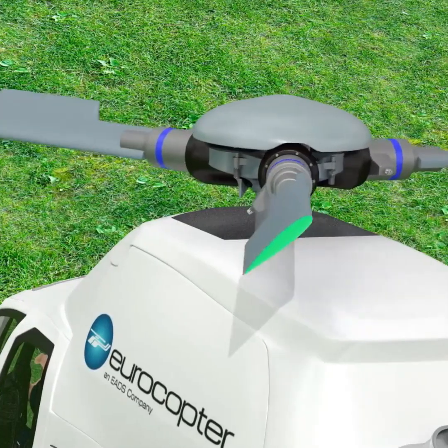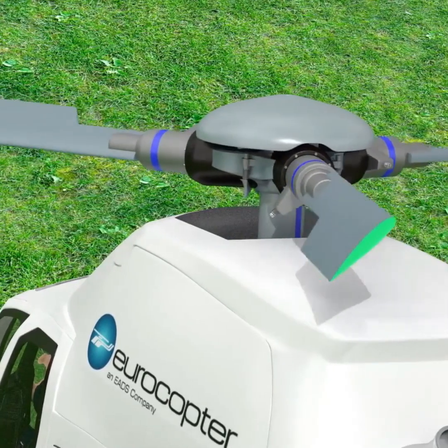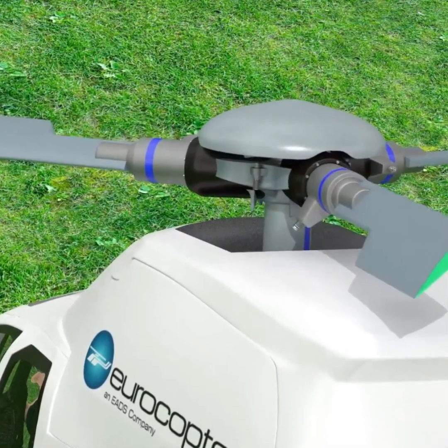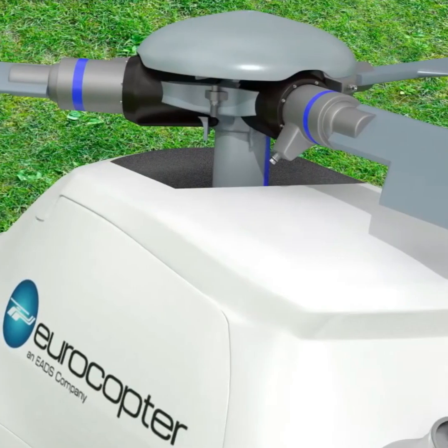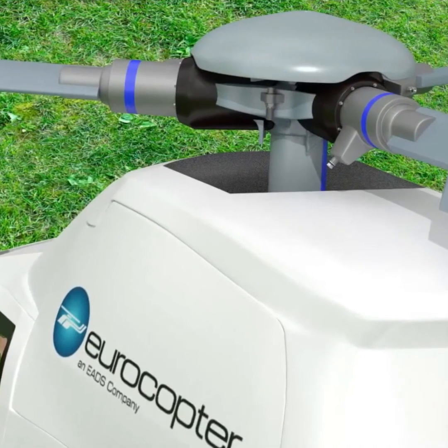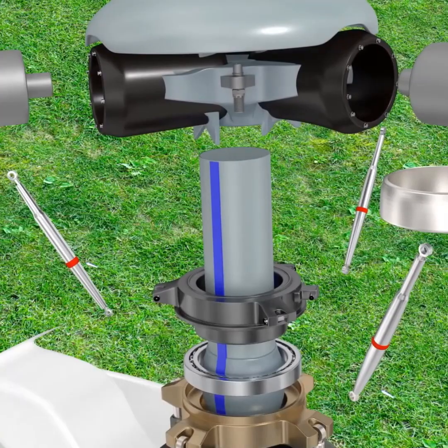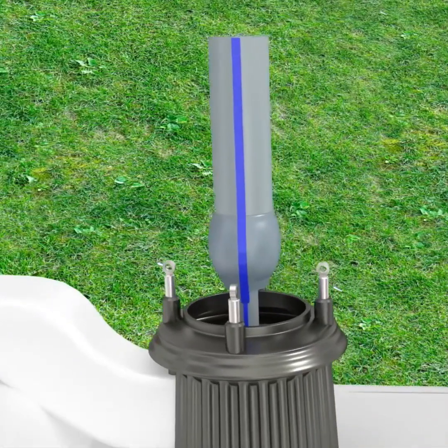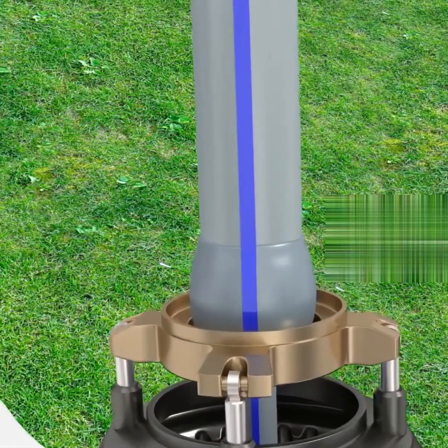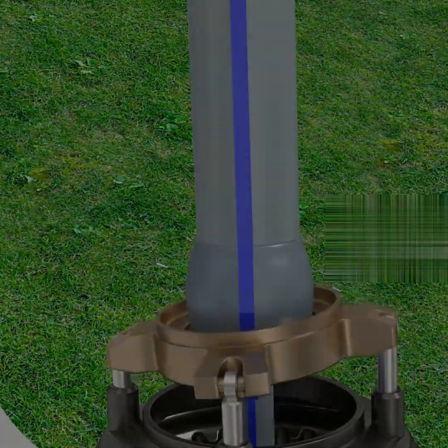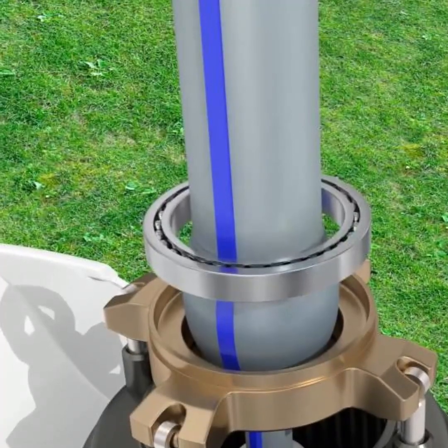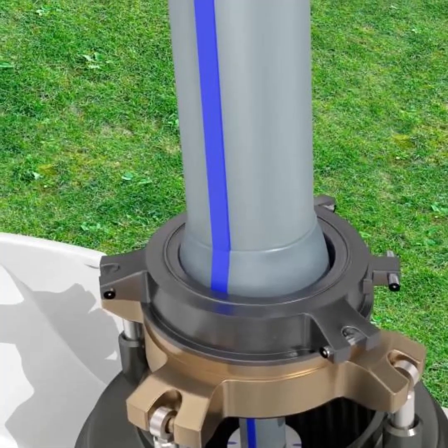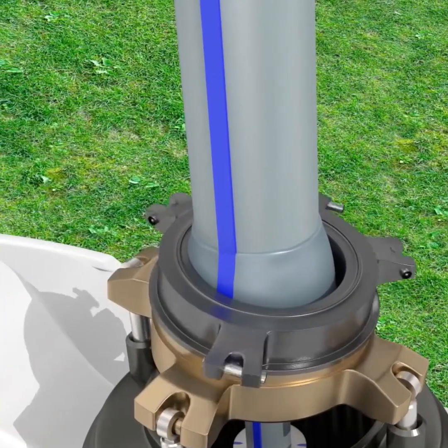To ensure an equal distribution of thrust, the blades must continuously change their angle of attack to maintain a specific position. This complex process is made easier by the swash plate principle. Let's examine the exploded view and first understand its basic components. The lower swash plate does not rotate but can move and tilt as shown. The upper swash plate is mounted on a bearing on the lower swash plate, enabling it to receive the movement of the lower swash plate while rotating independently.